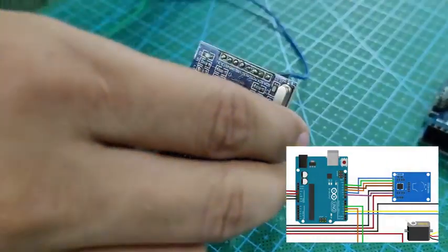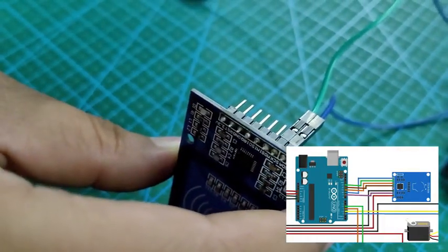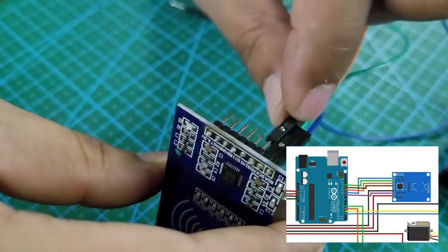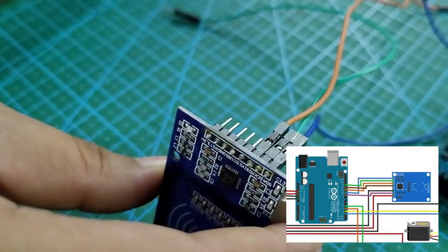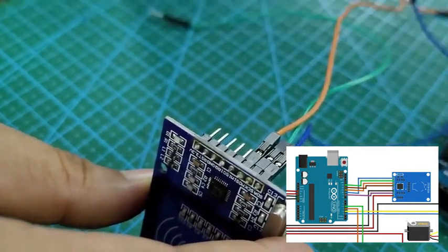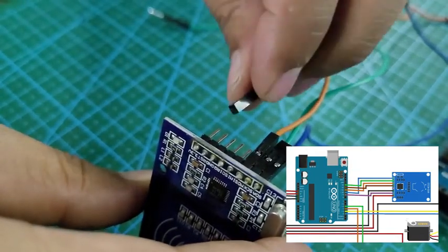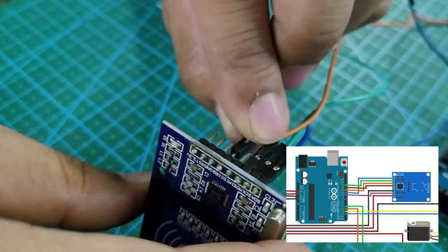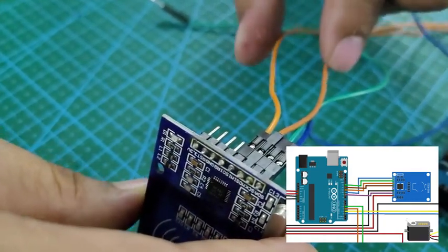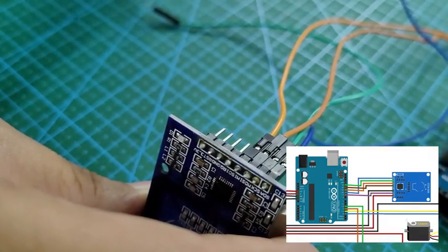A blue jumper cable for SDA, and we are trying to match the colors of the jumper cables to the circuit diagram, so it is easy for us to make connections later. Only in this case we don't have the red wire, that is the fourth wire that we are connecting now. We didn't have one, so we are just using the same color wire for the MISO pin, but that's okay. You can always use the red one, and also check if there is any confusion, which wire is coming out of which pin.